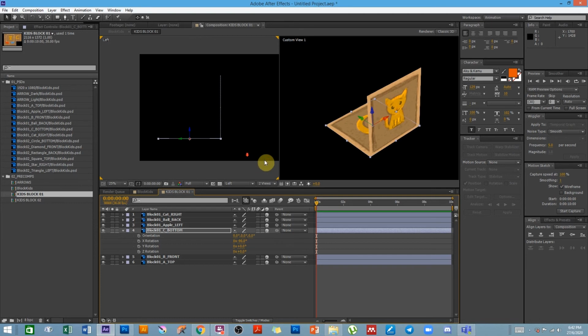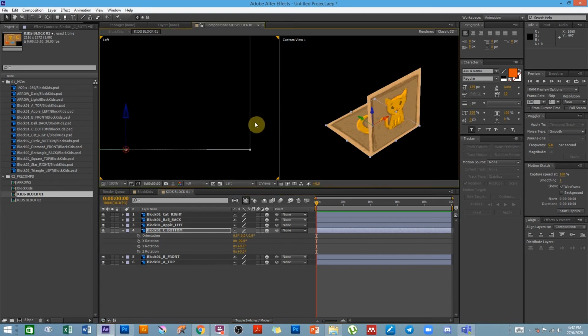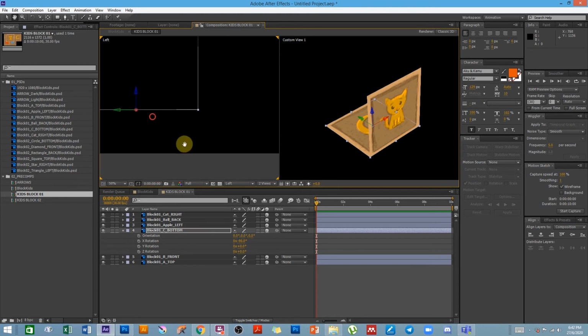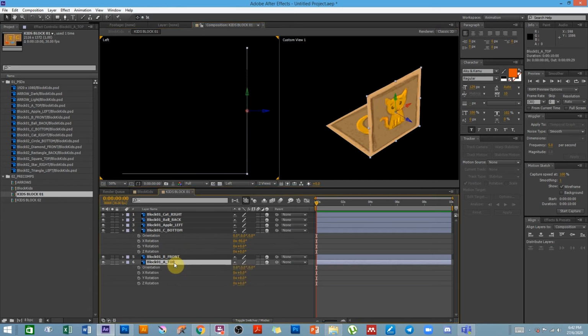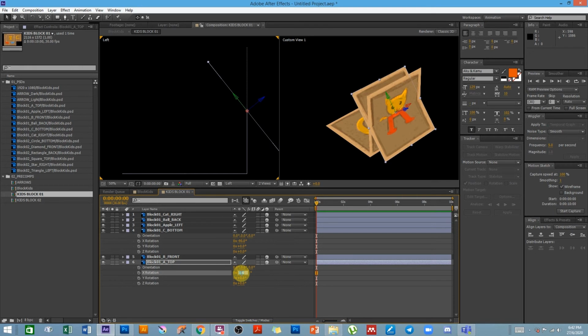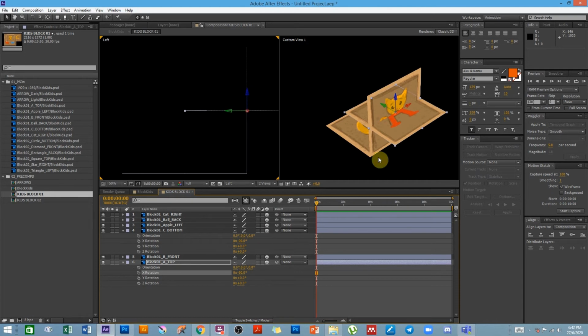Okay, so let's just check if the corners are snapping nicely. Over here, zoom in. I'm zooming in with the roller on my mouse. Okay, now to do the top, pretty much the same. Press R, X rotation, rotate to, you can be minus or positive 90 degrees, but negative 90 is going to make your A face upright, so that's good.